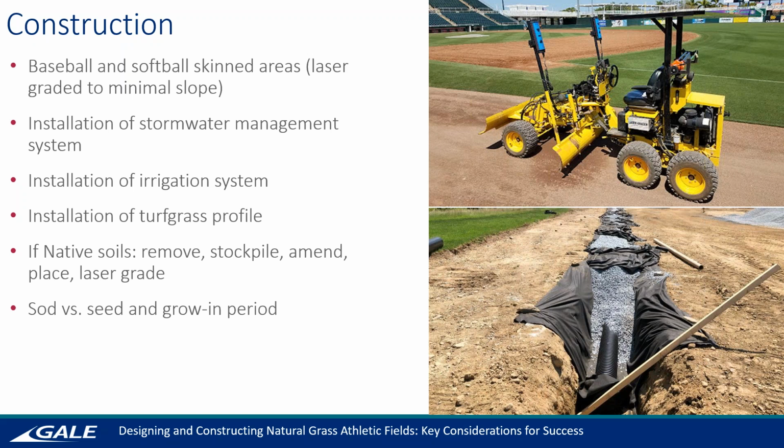For example, if this is a native and amended soil, you would be removing it, stockpiling it. You would be amending it based on what testing results were and the recommendations, whether it's adding more organic, any type of nutrients to it, the right amount of sand to create the best growing media you have, and then you're placing it back down, you're laser grading it, and then you're doing sod versus seeding and your growing period.